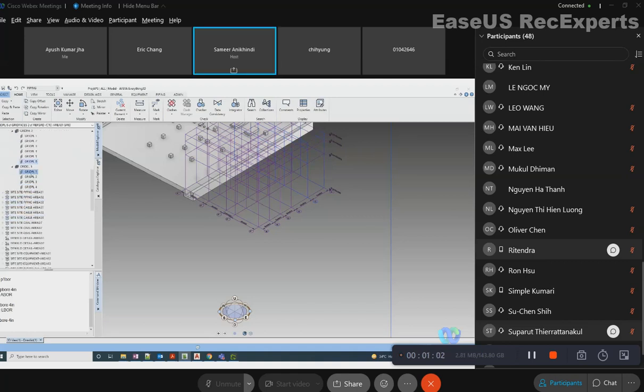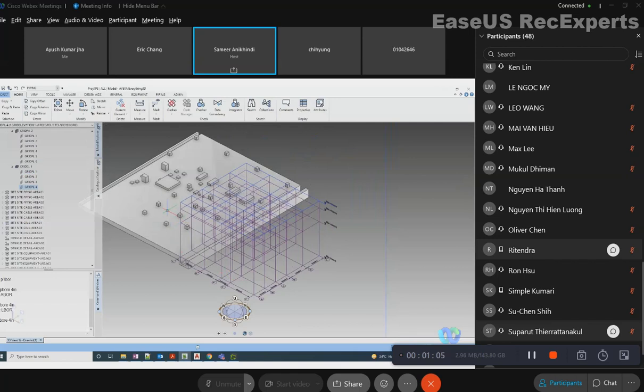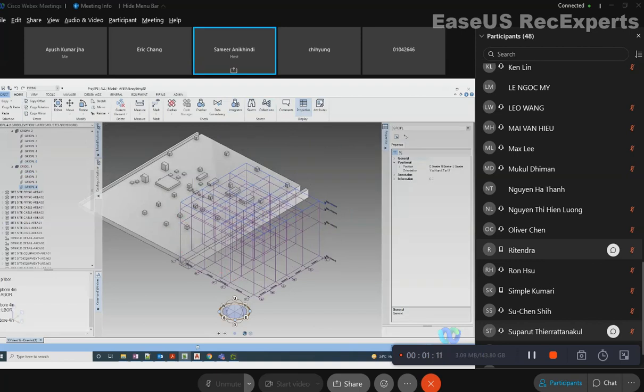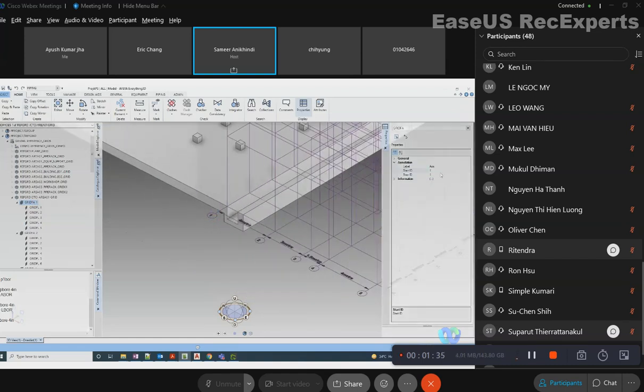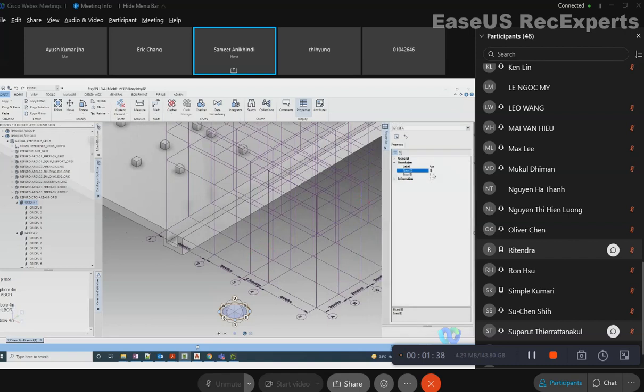Then elevation grid planes. So if you open properties, or you can open attributes as well. Properties for grid, or each grid area, you have this annotation. So this is my X planes. This is my Y planes. So you have start ID and step ID. Start ID is, you can see here it is 1. So 1 was specified. Automatically it takes 1 by default. And step ID, what will be the increment of grid numbers? So 1, 2, 3, 4. So that's an increment of 1.